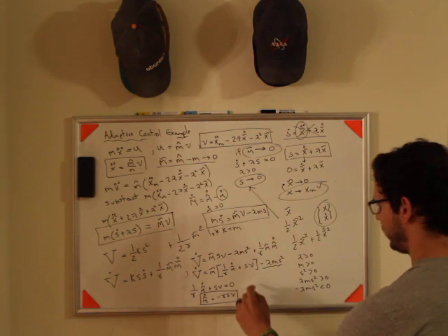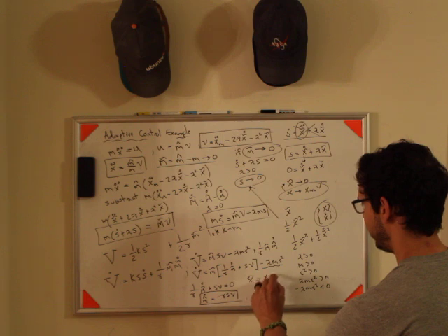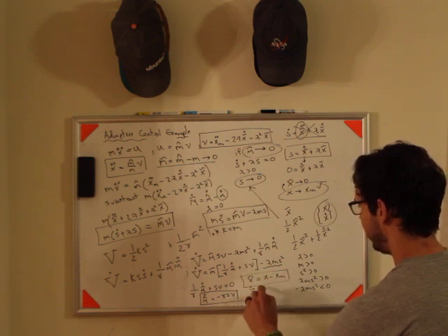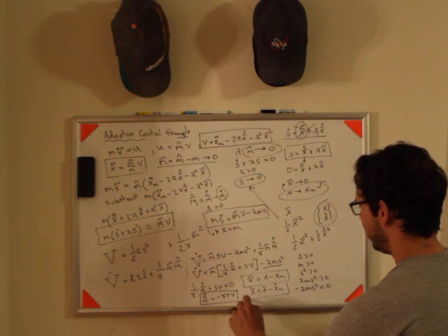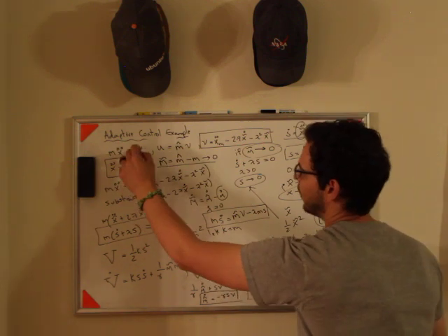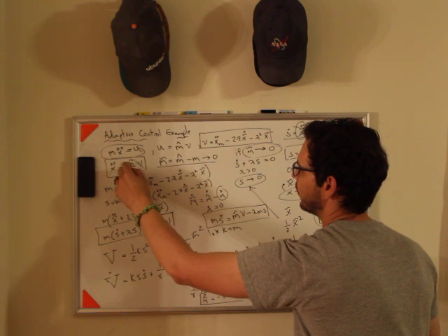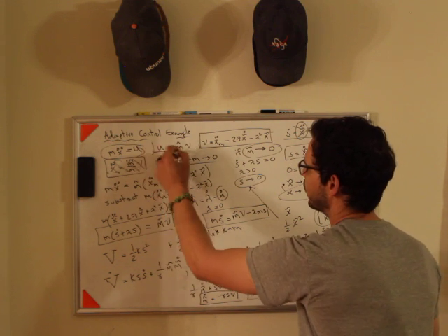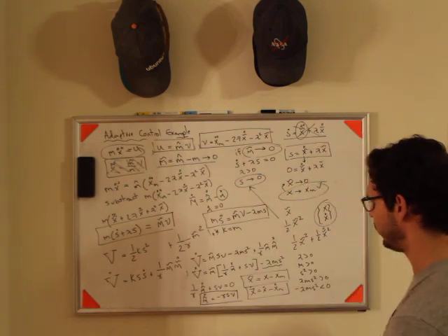I don't think I have that written down. X tilde is just x minus xm, and then x tilde dot is just x dot minus xm dot. And then x dot and x are here from your equations of motion. This is a closed loop, so you don't need to simulate that. And then here is your control law u.